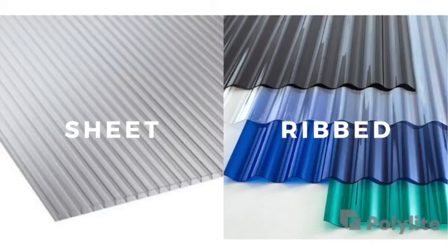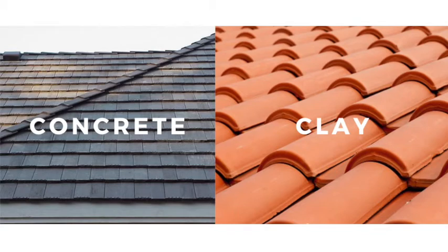Next, we have plastic roofing. The corrugated or ribbed roofing and sheet roofing are the two types of plastic roofing. The corrugated roofing is ideally used in sites of high salinity levels. These are corrugated sheets that are manufactured in the same widths and lengths as metal sheet roofing. On the other hand, the sheet roofing uses polycarbonate sheets which are ideally used in greenhouses, patios, other sheds, and skylights.